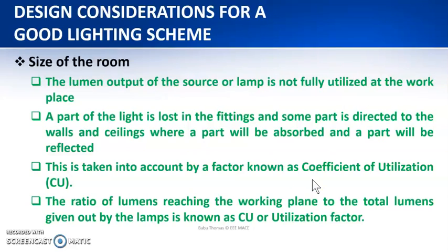Next is the size of the room. Not all the lumen output or light output from the lamp will reach the work plane. We have already discussed in the previous lectures that some amount will be reflected to the wall, to the ceiling and to the floor, and only a portion of the light output from the lamp will come onto the work area or the workplace.